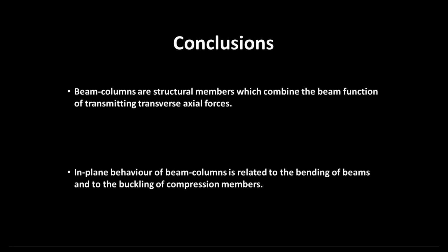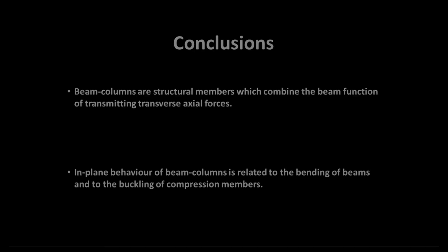From the conclusions, what we learned: beam columns are structural members which combine the beam function of transmitting transverse forces with the column function of transmitting axial forces. In-plane behavior of beam columns is related to the bending of beams and to the buckling of compression members.